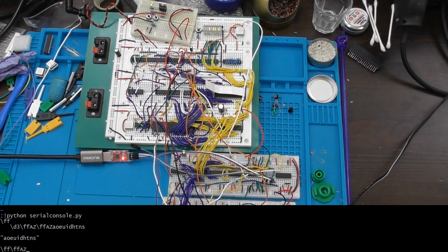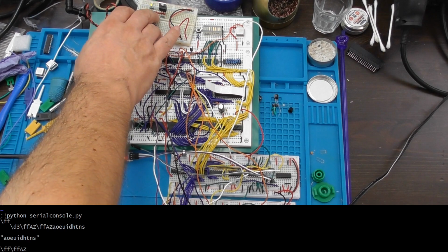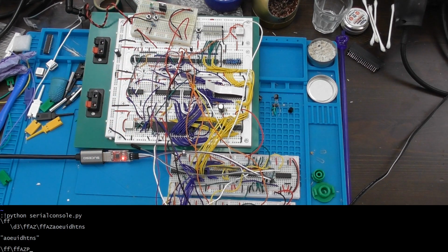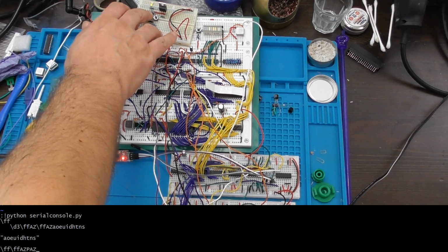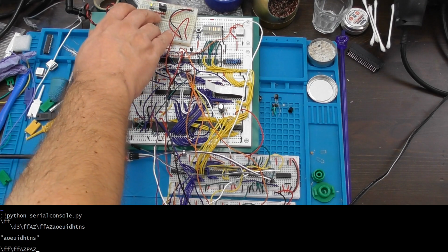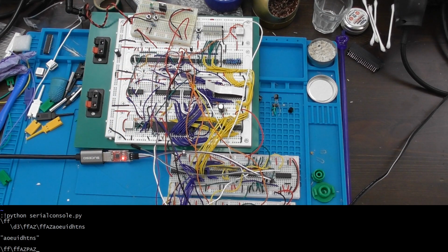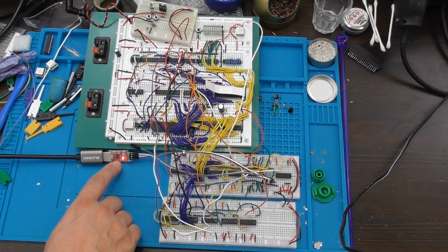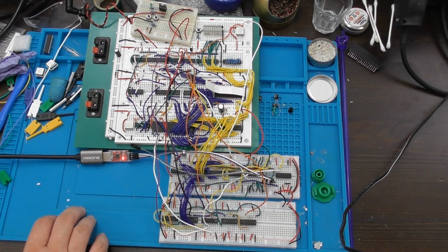And that is looking a bit better this time round. There was some junk printed when I turned it off. So that time it printed a P when I turned it off. And turn it on again. Yeah, just AZ that time. Now turn it off. And nothing that time. It is something I am observing. When the power goes off here, sometimes odd characters seem to get sent through to the PC. In this case, the blue light's not on here, so that tends to be a good sign, but I'm not sure exactly what that's about. Probably something to do with the resistor network not being great. But yeah, this is functional. Like I said, there may be a couple of glitchy things to debug here, but it is mostly working.